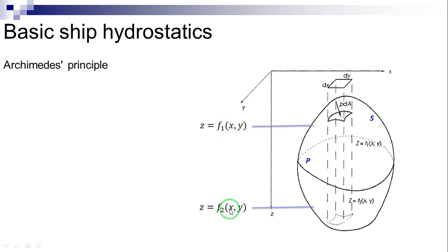The hydrostatic force on an element dA of S1 is P times dA. As we can see here, note that pressure at a point is the same in all directions, and this statement is known as Pascal's principle. This force is directed along the normal N to S1 in the element of area.